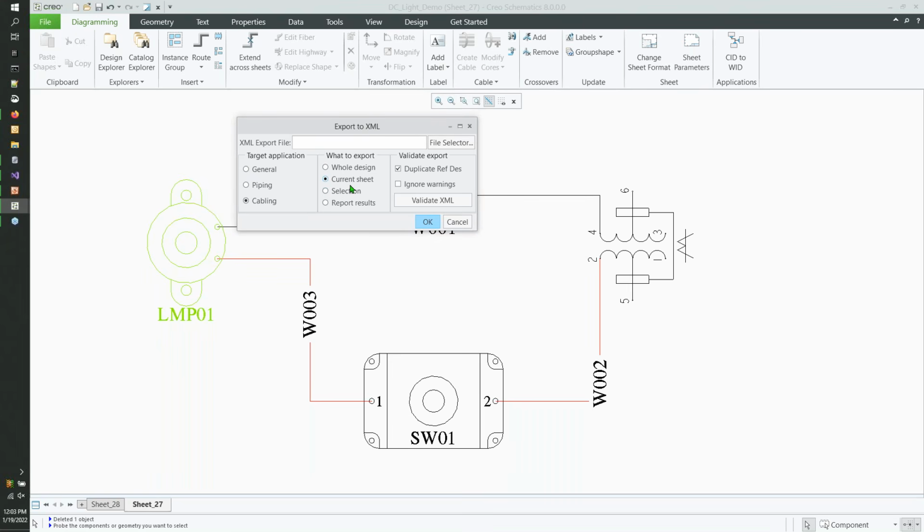It becomes daunting for users to deal with implications of logical data in a multi-sheet layered export inside of the parametric world, because when we transition into the parametric world, we forego the elegance of our design explorer here inside of schematics. The parametric world has one 3D assembly that everybody's building stuff onto. We don't really have a design sheet explicit to a specific harness or a specific part of schematics context design. So in order to not be so daunting,